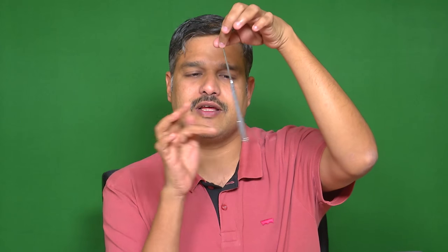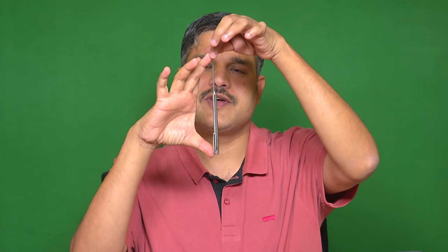In summary, what we have discussed in this module is degrees of freedom. First we discussed static indeterminacy, and second we discussed kinematic indeterminacy. Kinematic indeterminacy means the number of independent degrees of freedom which are required for defining the system. For example, for a pendulum, only theta is needed for writing the displacement. L is fixed, so if we have theta, we can find the x and y coordinates of the system at any point of time. So, this is a single degree of freedom system.